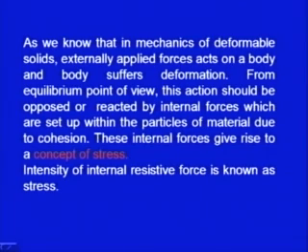And that is why you see the system is in equilibrium even under the variety of forces, because there are certain resistive forces set up within the object. These internal forces give rise to the concept of stress, because you see we apply the force through different lines of action and the body is under equilibrium. That means there are some internal body forces being set up.